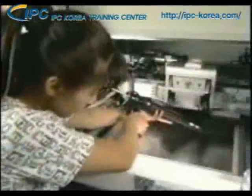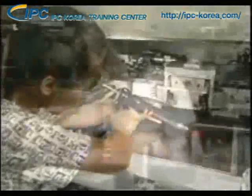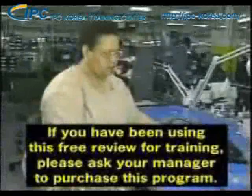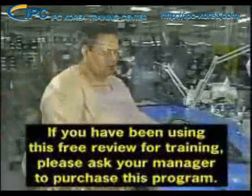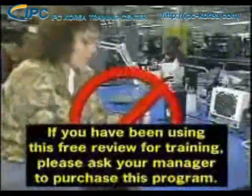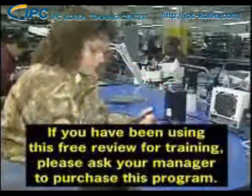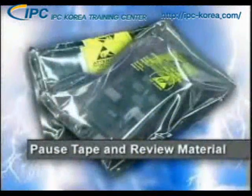When conductive smocks are not provided, you'll need to be aware of what you're wearing. Clothing made of cotton, rather than wool or synthetic materials, will help control ESD. Also, you should avoid wearing loose clothing that drapes down and may come into contact with ESD-sensitive devices. Let's stop and review the material we just covered.